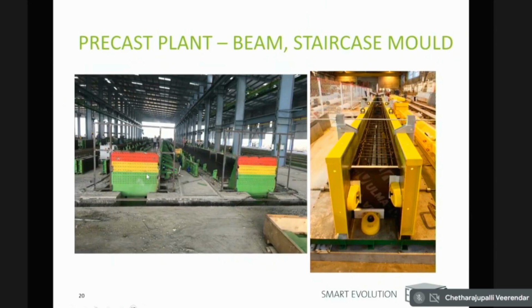These are pre-stressed beams production. This green, yellow, and red element, what you can see here, is the abutment. These abutments carry a force of about 750 ton, and these abutments are carrying these forces to the bottom on the foundation, and that is a steel plate going equally down, plus bolted and welded to the foundation, so that when you are pulling these strands, there is a 750 tons of force being used when you are pre-stressing this, and that requires to be taken care by the foundation which is there.